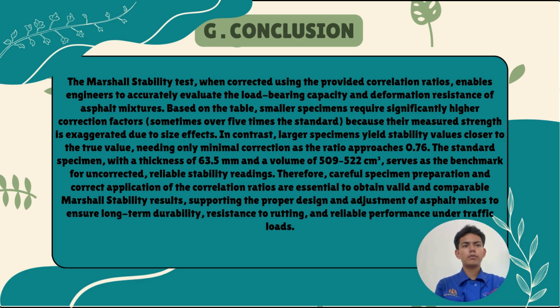In contrast, the larger specimens yield stability values closer to the true value, needing only minimal correction as the ratio approaches 0.76. The standard specimen with a thickness of 63.5 mm and a volume of 509 to 522 cubic centimeters serves as the benchmark for uncorrected, reliable stability readings.